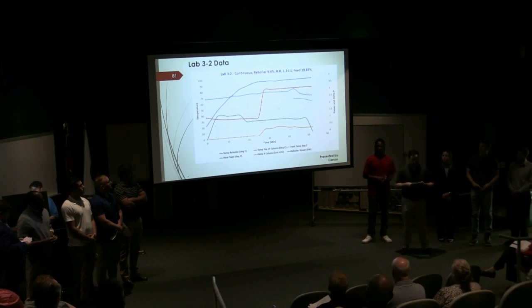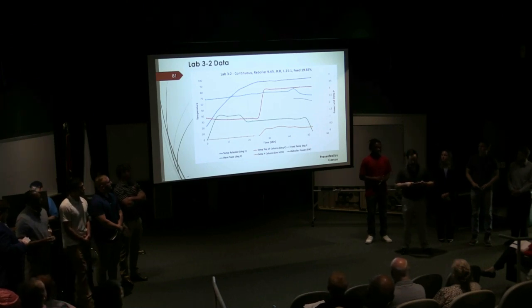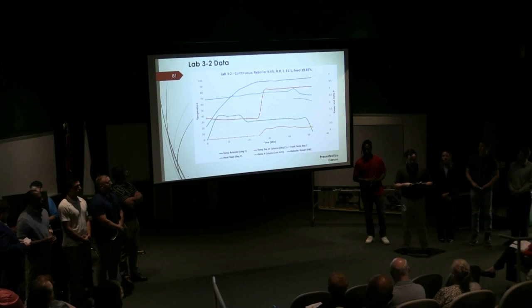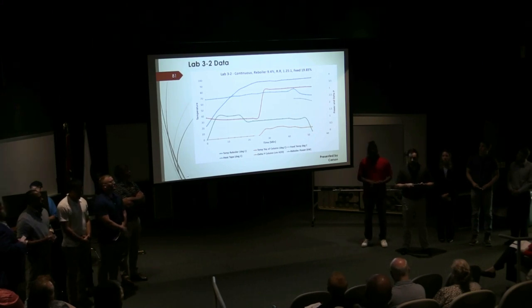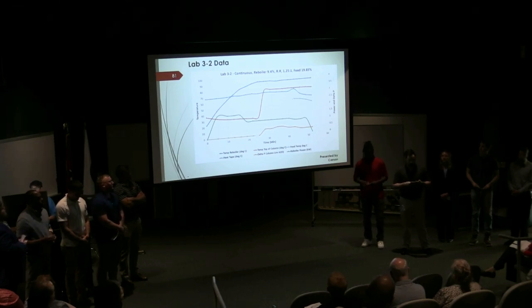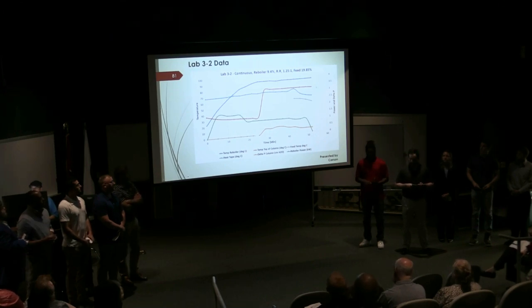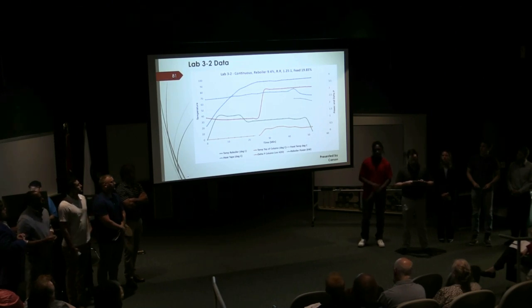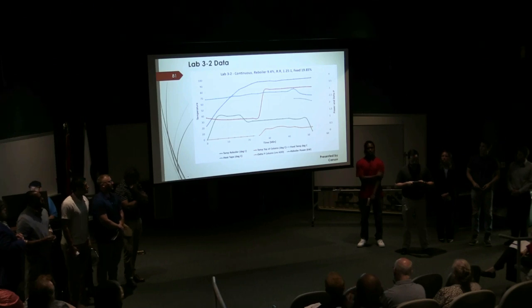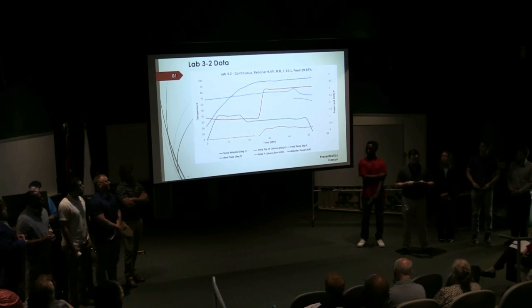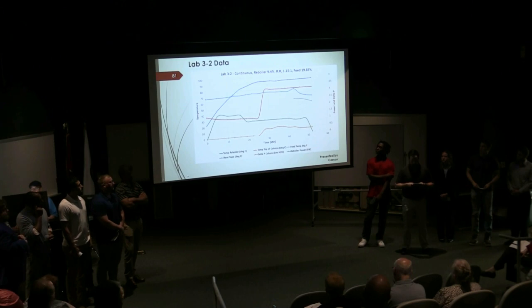So for this experiment, we forgot to increase the heat tape power to 40%, and we ran at 30%, but our heat tape temperature did rise. The data was incomplete though, since we started to record that temperature late. But overall, the run was stable, as indicated by the temperature at the top of the column. We adjusted our reboiler once, and the pressure trough was fairly constant for the whole run, as indicates a consistent production rate.